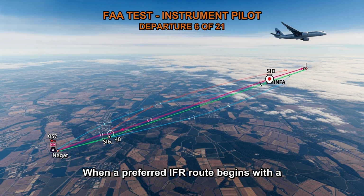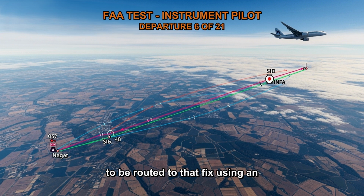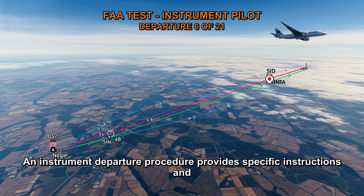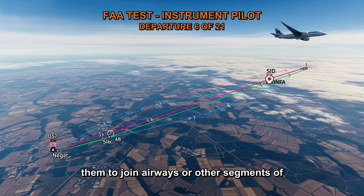When a preferred IFR route begins with a fix, the typical procedure is for departing aircraft to be routed to that fix using an instrument departure procedure, DP, or radar vectors. An instrument departure procedure provides specific instructions and routing for aircraft departing from an airport, guiding them to join airways or other segments of the route.